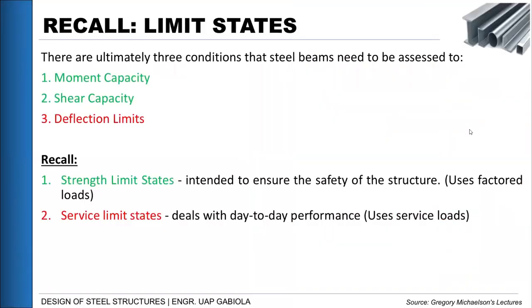So let us recall the limit states that we have discussed. Again, we are already through with the moment capacity of our section. Now we will try to focus ourselves with shear capacity and deflection limits. As a reminder, for strength limit states, meaning we are ensuring the safety of the structure, we use factored loads, and shear capacity is a strength limit state.